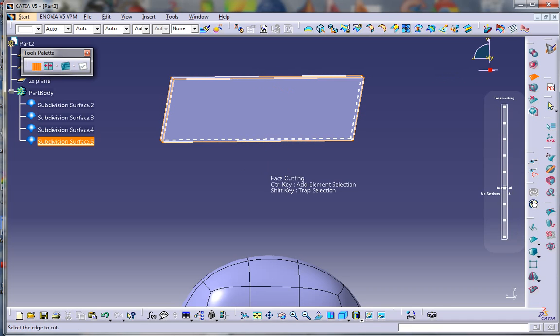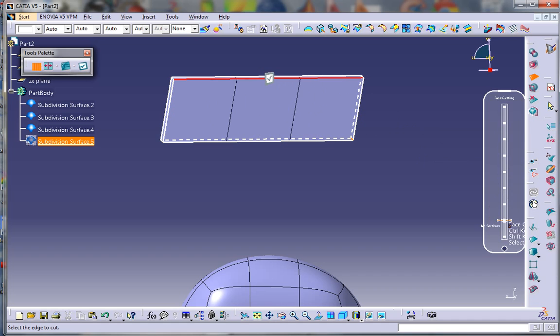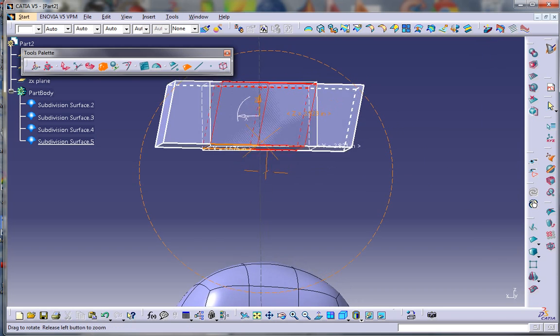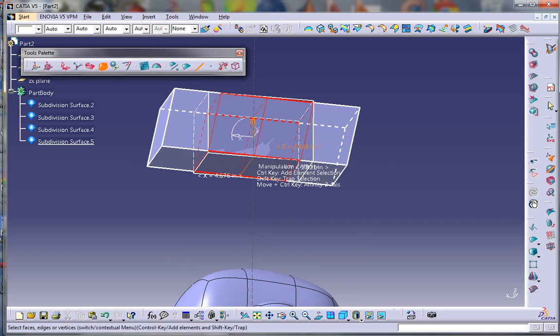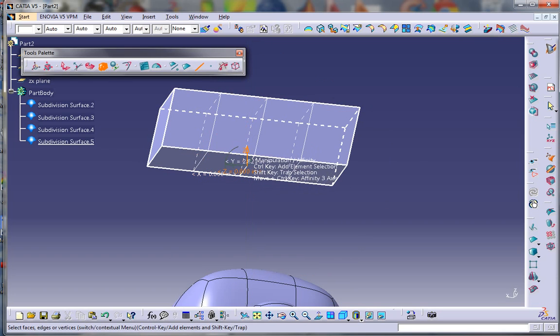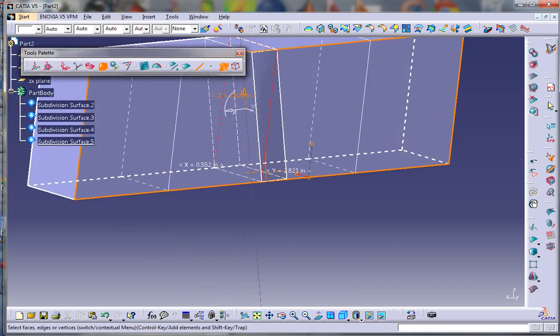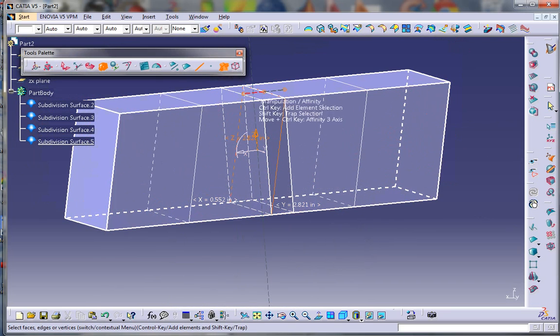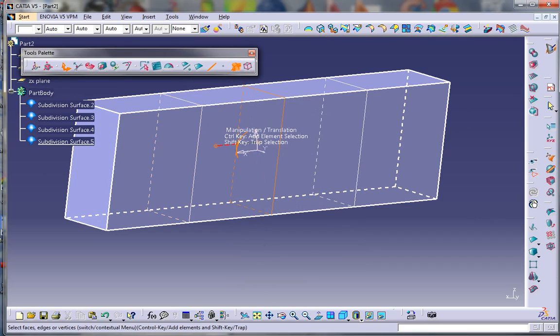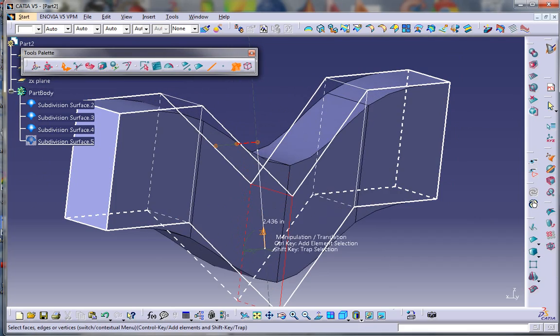And we're gonna make some face cutting. Actually, 4 is okay. We hit enter, and now I will select only this one, only this side. Actually, I'm going to select this propagation tool, which is really helpful. I'm going to select it. What this tool does is it selects the interior of the lines. So I will just move it down.